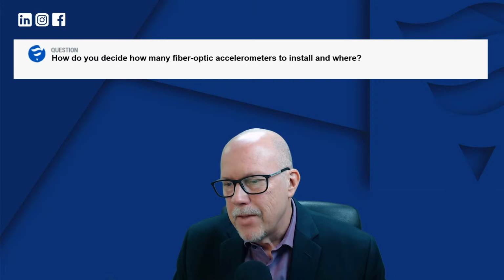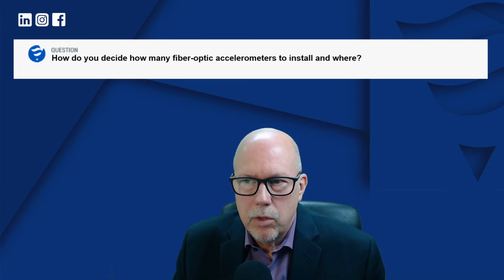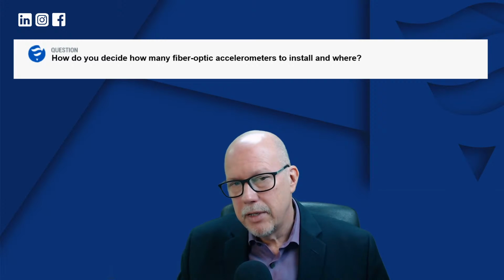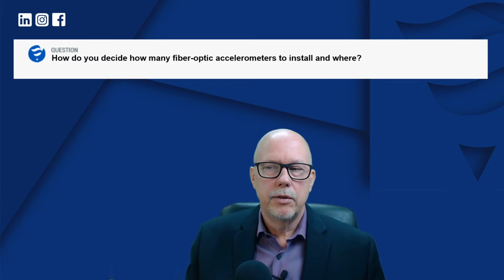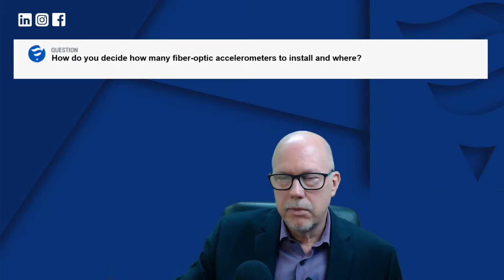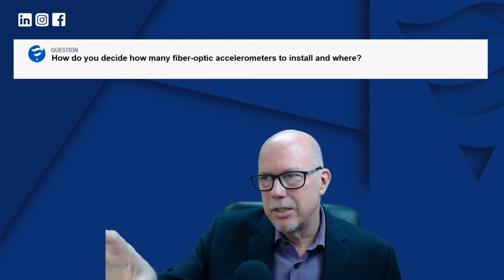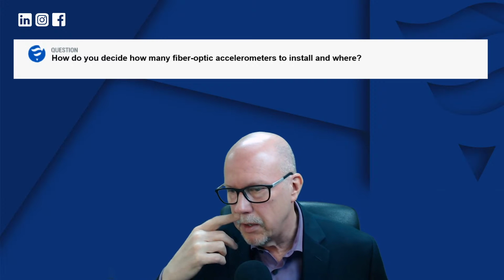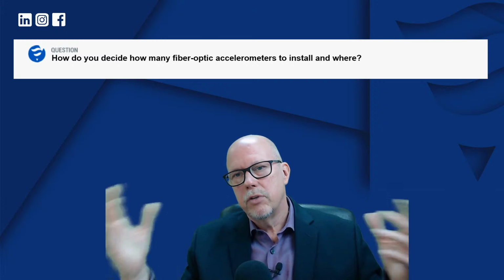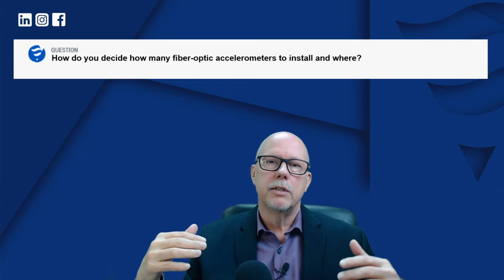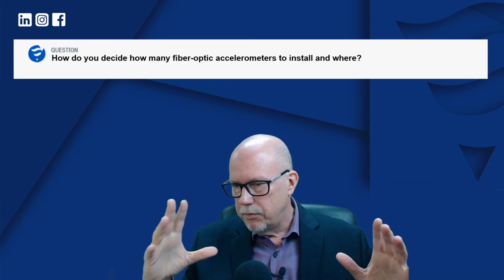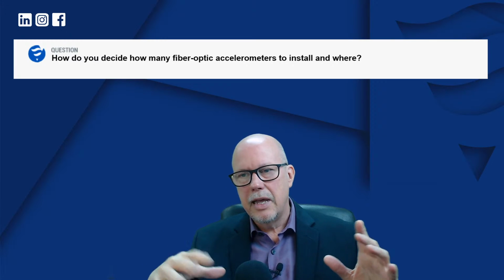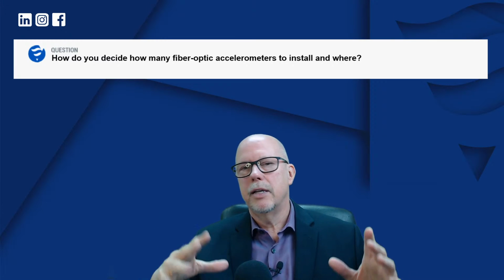I guess what would lead you to decide how many sensors and where would be, again, some of that evidence we just spoke of. If you go in there and you have localized dusting somewhere, you might want to focus your end-winding vibration sensors in that location, maybe put a few others in reference somewhere else. If the evidence of dusting is everywhere, then what I would recommend is you do bump tests. In reality, if you suspect that you have end-winding vibration issues, I think that at all major outages you should plan for bump testing.